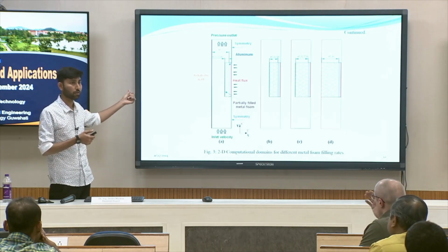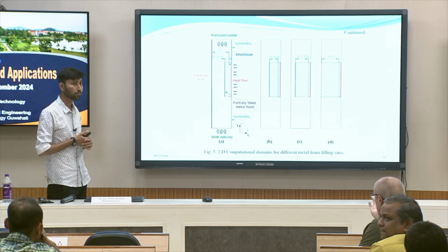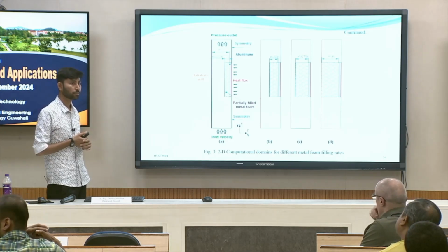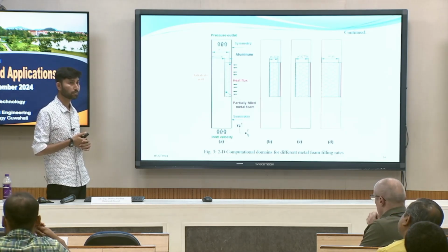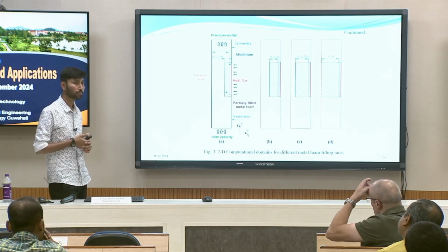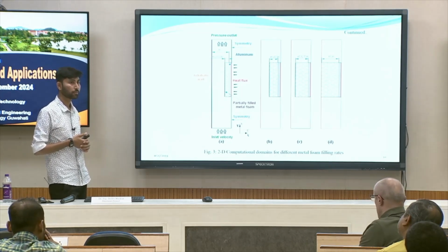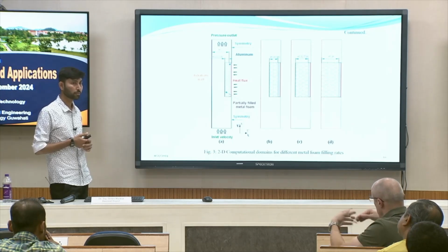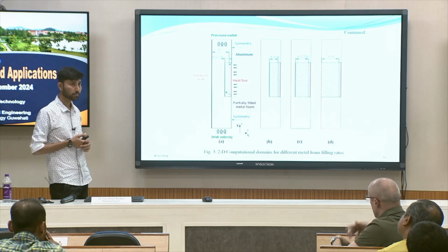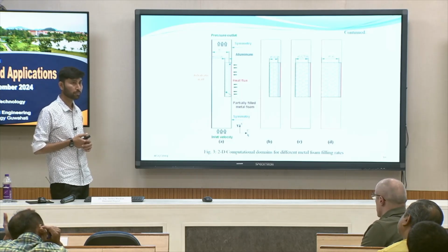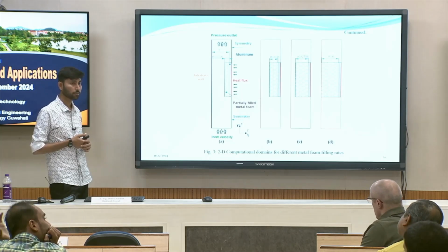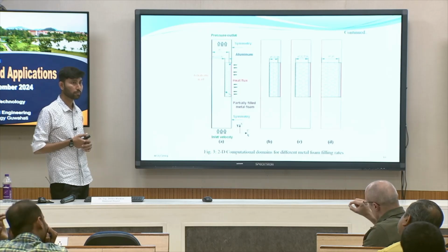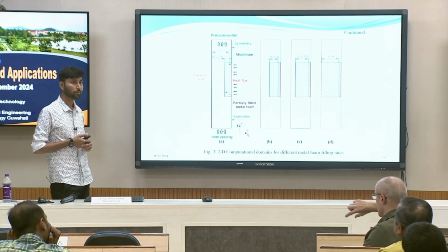When you look at Fluent, you can represent porous structures by some specific parameters. Let's say in this area I have a porous structure with this porosity, this density, this heat transfer coefficient, and so on. So you do not resolve it very finely, because you're not interested in what is happening inside the porous structure.